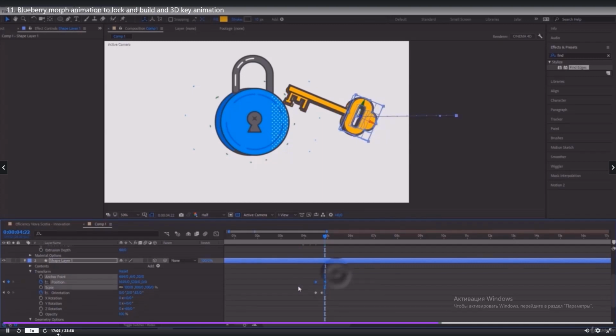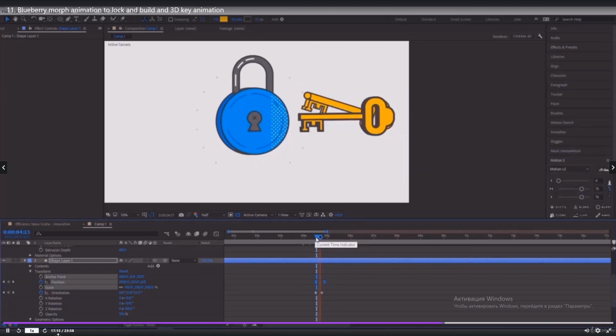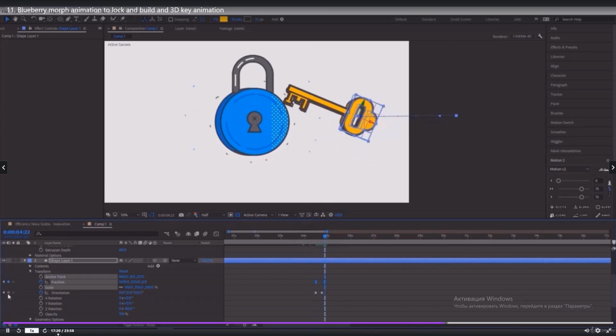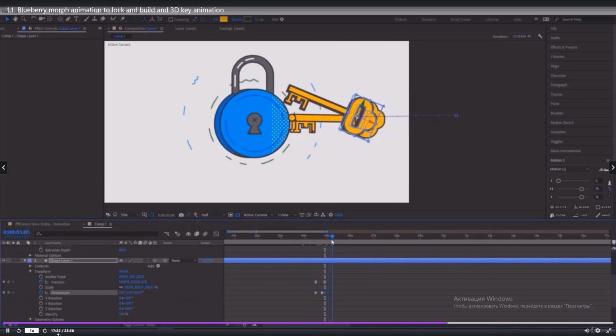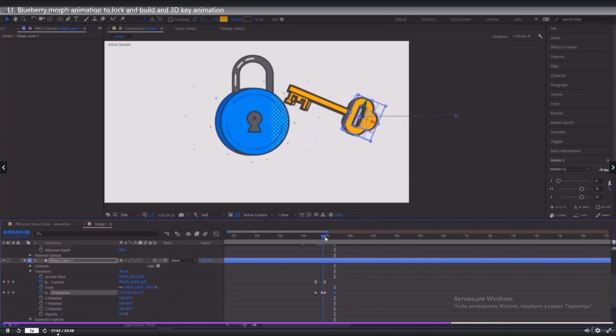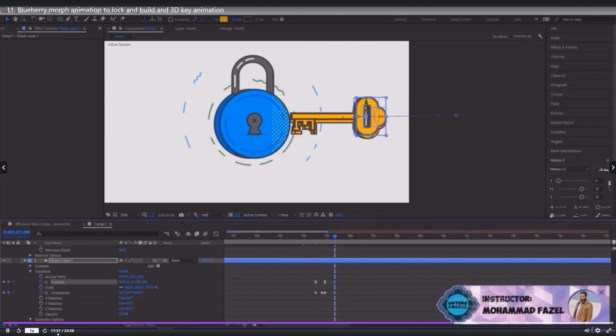What kind of easing should we use for this? Use the anchor easing from the motion tools. Then the key starts rotating again on this point until it gets here. Turn it to 0. Adjust its position. Easy ease these 2 keyframes.